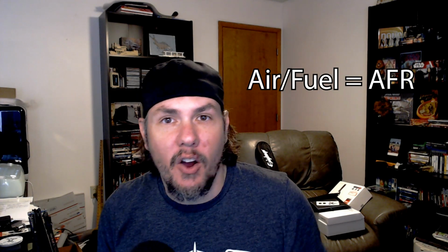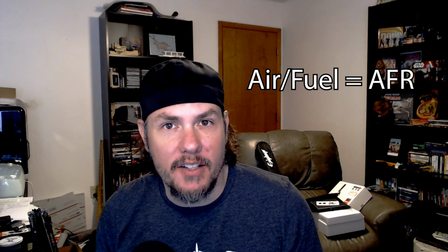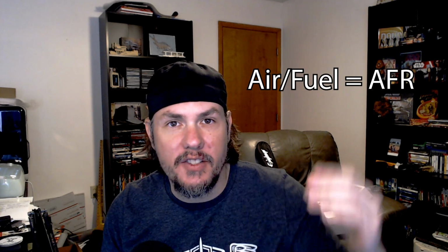So, in order to really understand how our fuel systems work, we have to take into account the X over Y equals Z formula, where X is air, Y is fuel, and Z is our AFR. We are tuning for X, our airflow. Z is more of a constant. Our fueling, we consider a constant, and we adjust our airflow up and down in order to get the AFR reading that we're looking for whenever we're tuning.